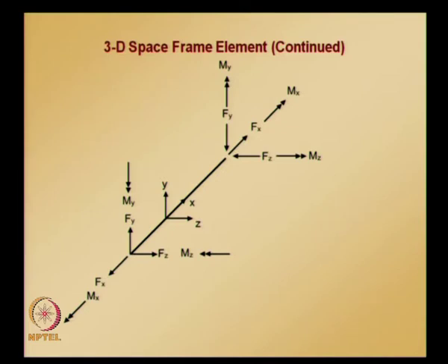internal forces and moments, because finally we will be using this sign convention after we calculate all the internal forces, that is all the 3 components of forces at node 1 and node 2, and also all the 3 components of moments at node 1 and node 2. We can use these sign conventions to draw the free body diagram and also to draw bending moment, shear force, axial force and torsional moment, such kind of things we can draw using the sign convention.